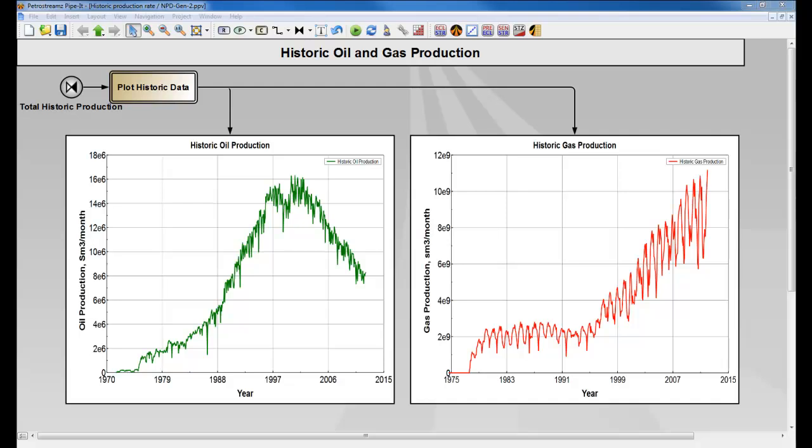Now we've seen and have access to historical production data from every field on a monthly basis. What can we do with this data other than just looking at it? As part of Kjetil's master's thesis research, he is using the Fetkovich-based decline curve models to forecast oil and gas production by field to generate a Norwegian Continental Shelf production forecast.